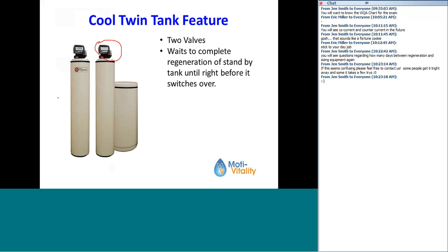And when I am home, it's just me and my 2 kids. So my softener only regenerates sometimes once every 2.5 weeks. If it was set up the way it could be set up, it would only regenerate every 2 or 2.5 weeks. That's a problem because it regenerates when it switches over tank. It switches over to the secondary tank and immediately goes through its regeneration. So that means I've got water sitting in the standby tank for 2 weeks or more sometimes.